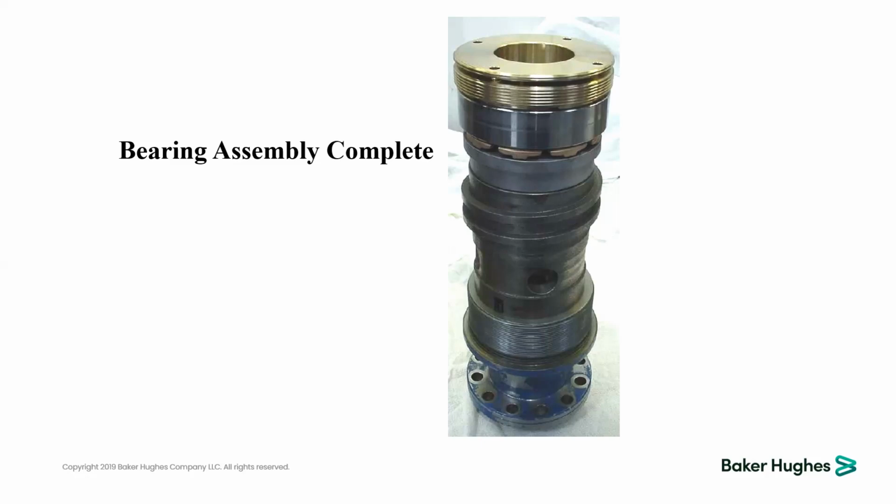Sometimes you can have only 3 bags without a labyrinth at all. Sometimes you can have the bag at the top and the labyrinth at the bottom. Based on each application, you have to use the proper configuration of the seal section. And you shouldn't standardize it unless your field and experience and wells are identical, or the difference is not critical to have it standard along your field. So you have to consider for each application the proper seal configuration.